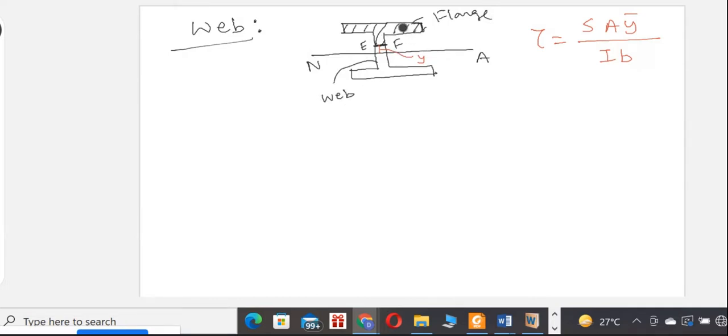First think about the flange part and everything about the neutral axis, then think about the small portion in the web, and then we can add those parts. So let me divide this A y bar as A y bar flange plus A y bar web small portion.